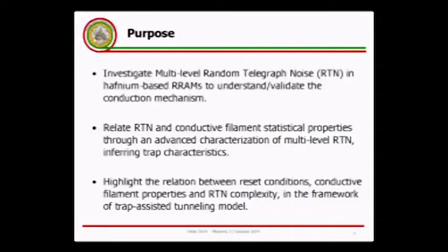During the last year, I focused my work on the analysis of complex multi-level random telegraph noise in these emerging devices, mainly to validate or to enhance the actual understanding of the conduction mechanism and the origin of the random telegraph noise itself. I successfully related the RTN statistical properties to the property of the conductive filament, which is one of the constituents of these devices. And I carried out an advanced characterization of multi-level random telegraph noise, successfully inferring the characteristics of the traps causing the random telegraph noise itself.